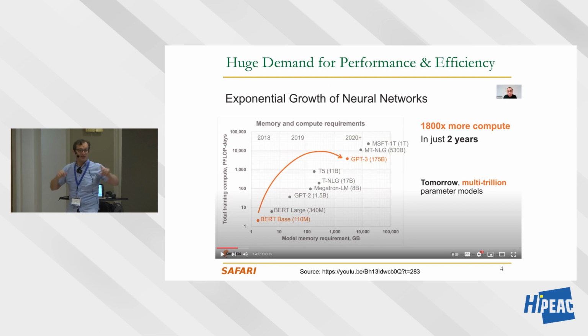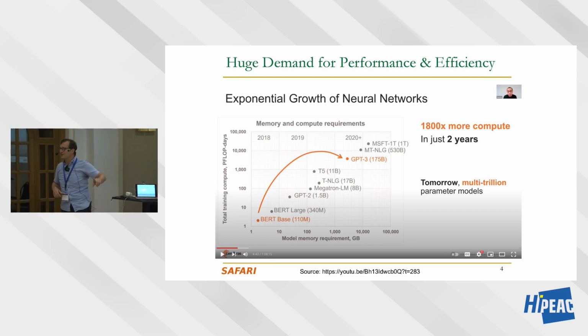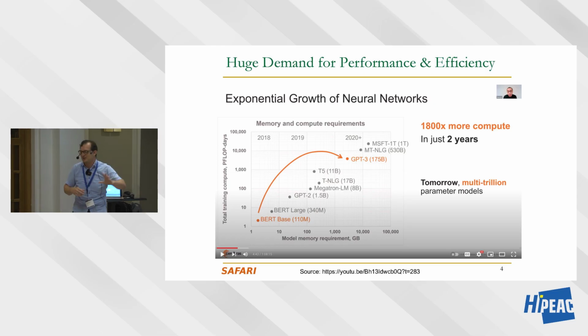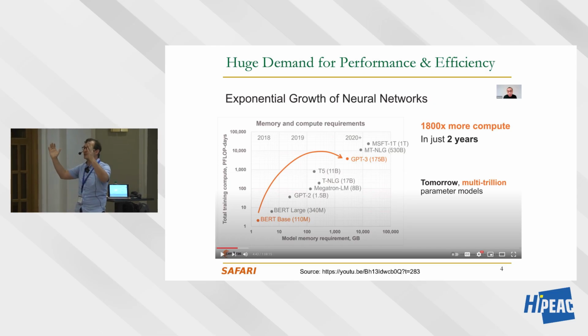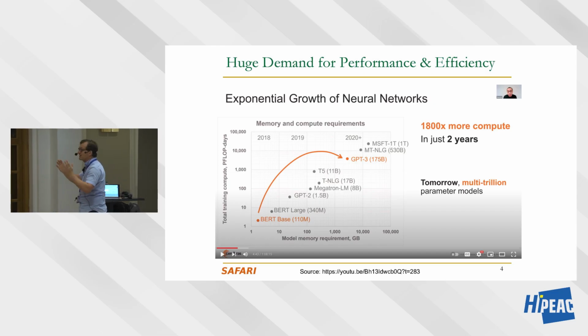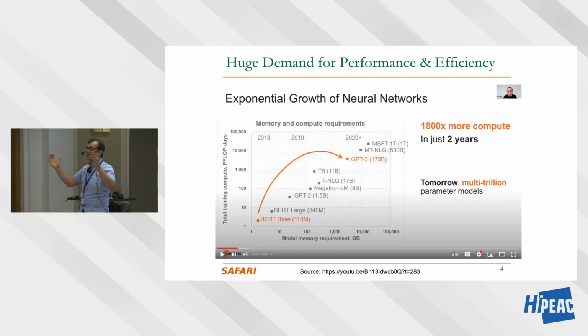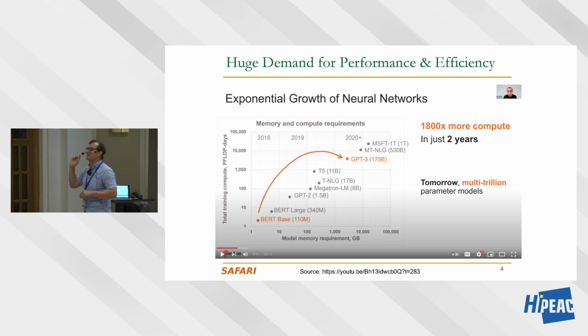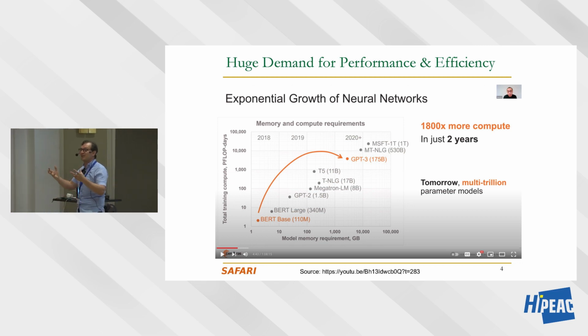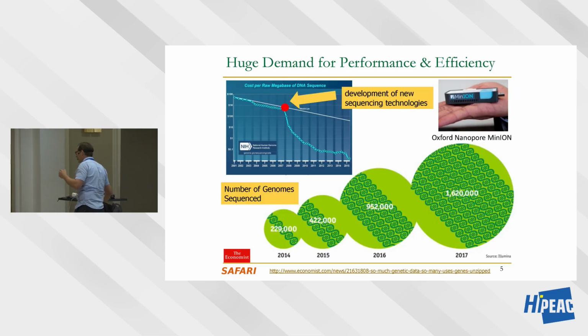And this particular picture is from Cerebras' CTO. Cerebras is still actually designing wafer scale chips, and their goal is to put a lot of compute and a lot of memory together at low latency. We may talk about that. They're putting a lot of SRAM, but the amount of SRAM that you can put on a chip today is very limited. In this case, they have a wafer scale chip like this big, and in that case, they have 80 gigabytes of memory. 80 gigabytes is nothing. This doesn't mean that they're not a great startup, in my opinion. I think they're trying to do something very, very interesting, except it's not clear if it will be able to cater to the large data sets that we have today, from my perspective. They may have a different perspective.